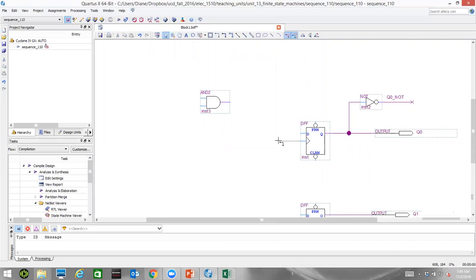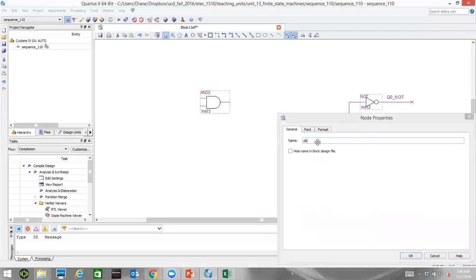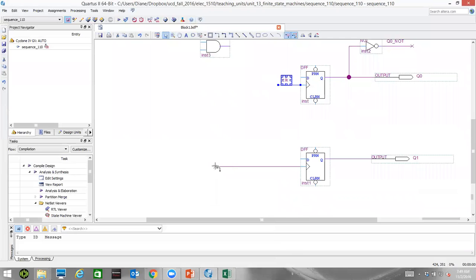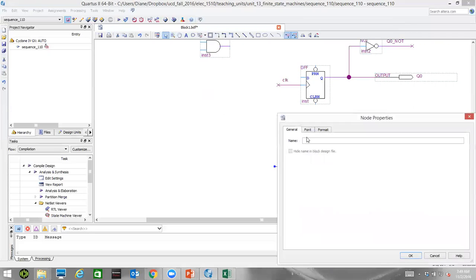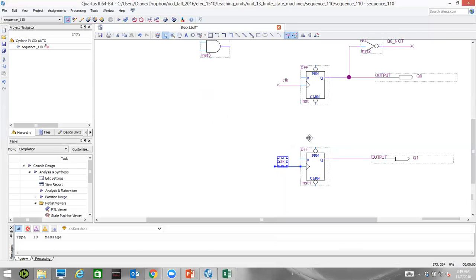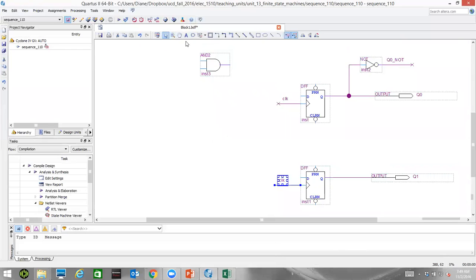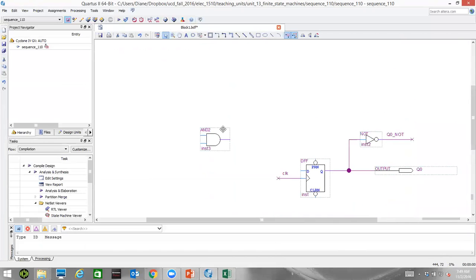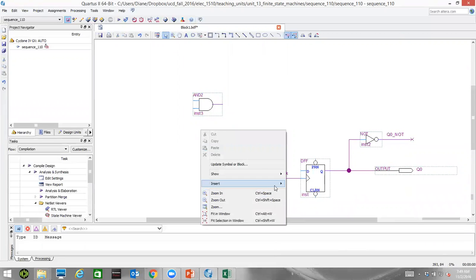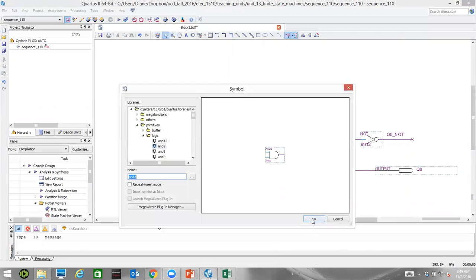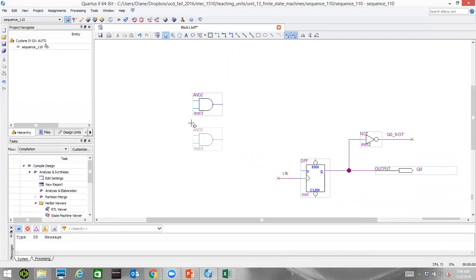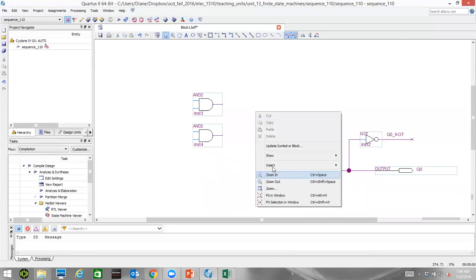I can wire these in like this. We won't have all these wires to look at. Shorten that up a bit. All right, CLK. That makes that clock connection from that input pin to these by naming the wire the same thing. I said now I want to drive D. I'm going to need another AND gate. Yeah, probably. And I'm going to need an OR gate.